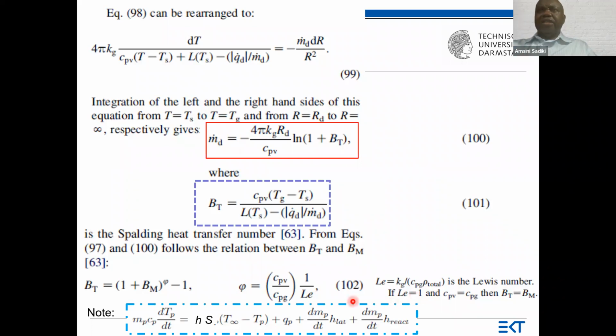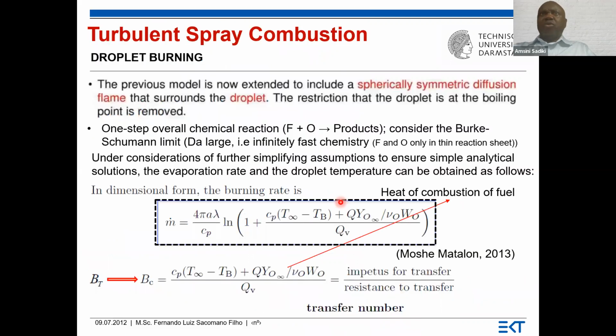differential diffusion, and for the evolution of the temperature of the droplets. So we have got these 3 terms, this one, the first one to warm up, and this is the latent heat, and it is the part due to the chemical reaction. This means that in this expression here, we will get an additional contribution due to the heat, and this quantity also will be completed by an additional term which accounts for the heat of combustion of the fuel.